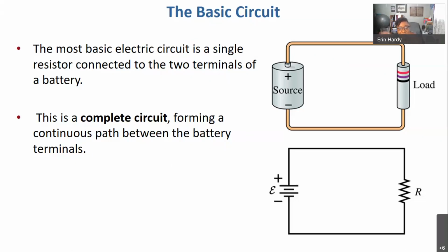And then there was another scenario that was essentially the opposite. I could have two very, very different capacitors, but if I wired them up so that they were in parallel with one another, that they had their own individual connection to the terminals of the battery, then their delta V's would be the same value. Q is what would change in that scenario. And we're going to run into some similar rules here with resistors. If I just have a single resistor and a single battery, this becomes really straightforward.